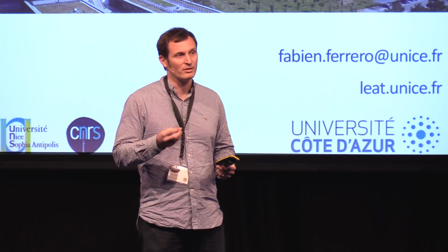I mean, a VNA is useless for a miniature antenna, because with a VNA you need a cable to connect your antenna, and the cable is going to influence a lot the characteristics of your antenna, and you are not going to measure the behavior of your antenna without the cable. So the best solution is to put your module in emitting mode, in continuous wave mode, and use a spectrum analyzer to measure the output power in different directions. Of course, if you have access to an anechoic chamber, it helps a lot. But if you are outdoors, for example, and very careful, you can have quite good results.